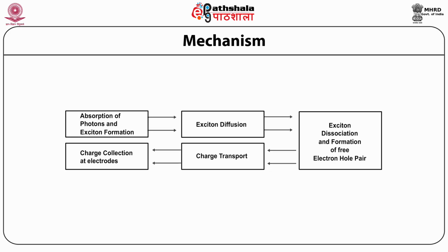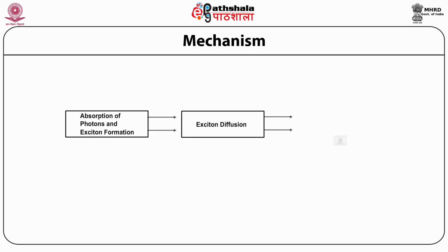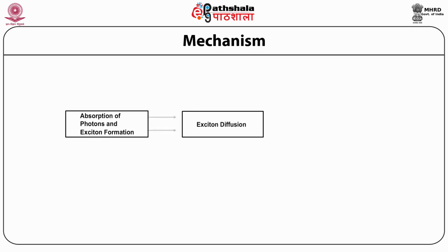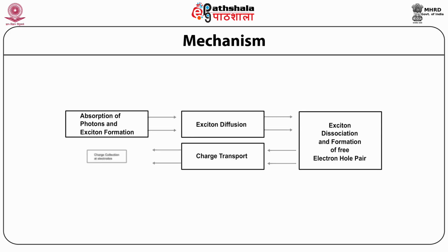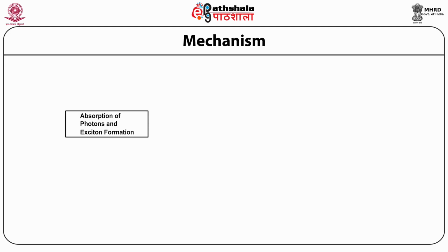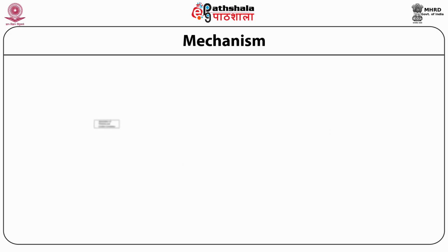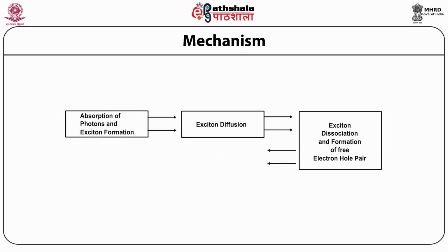The electrode metals are so chosen that they form an ohmic contact with the active layer to ensure efficient collection of the charges. The cathode work function is chosen closer to the LUMO level and anode to the HOMO level. While selecting the electrodes, one of them is generally chosen to be a transparent surface or substrate so that the incident light can reach the active layer.